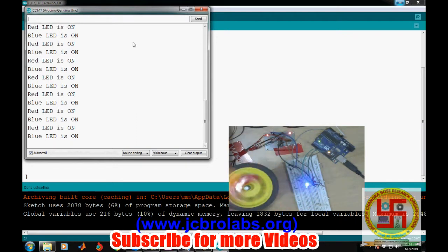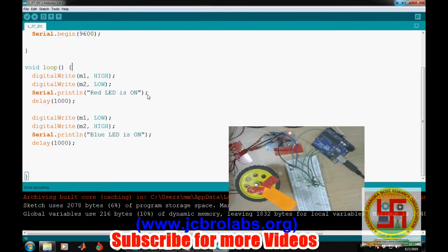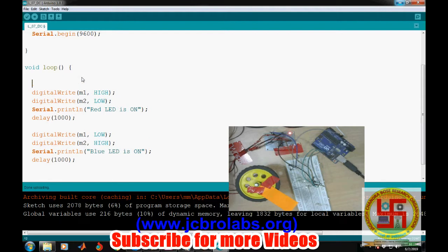For that we have to stop this Arduino, otherwise it will keep on running. So now what we want to do, we will be reading the data from the serial port, and if 1 is being sent, it will rotate in anti-clockwise direction, that means the red LED is on, and if 2 is sent, it should rotate in the clockwise direction.